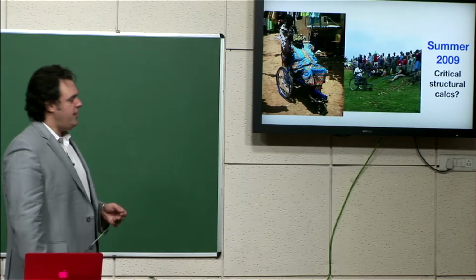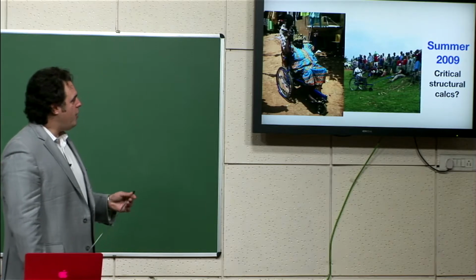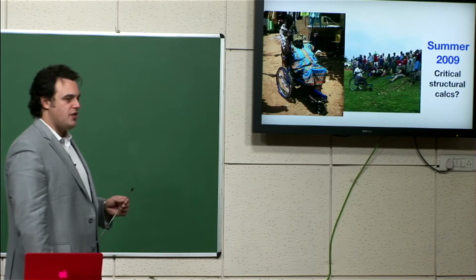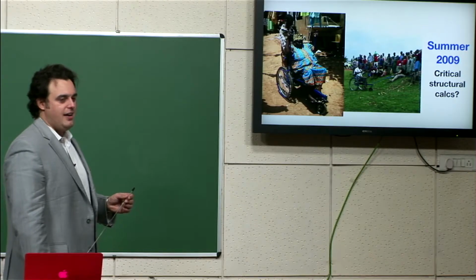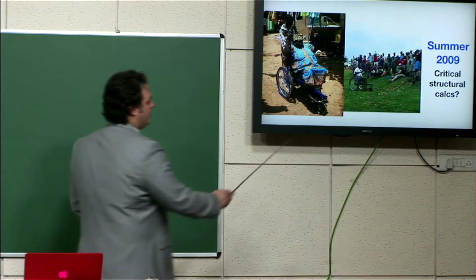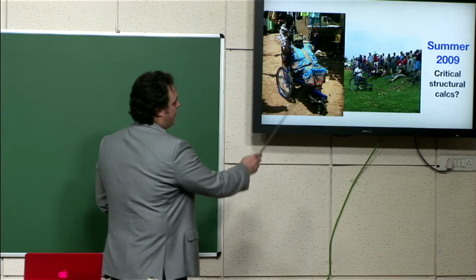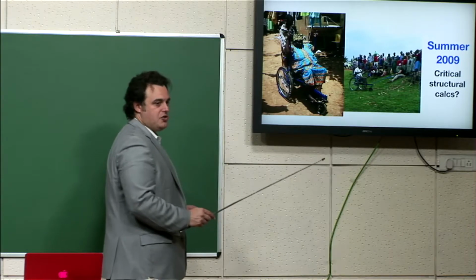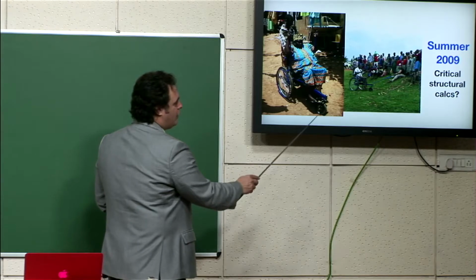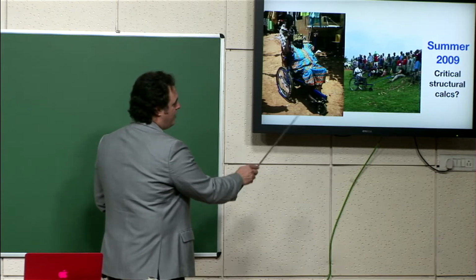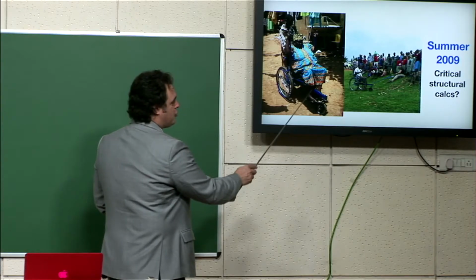The loads in the seat aren't tremendously large. Maybe I'll give you a little hint. Where do you think the highest stress could occur in the frame? Exactly. This is the only cantilevered structure in the whole frame. The rest of the frame, you'll see in some later pictures, is trussed. It's all a series of triangles. But this is cantilevered. So right here, even though the loads are rather small, we have a long length here. And so we had to think about the bending stresses in here.